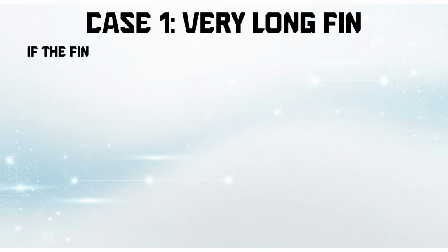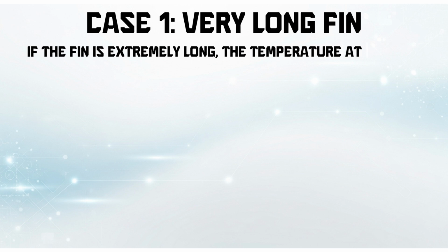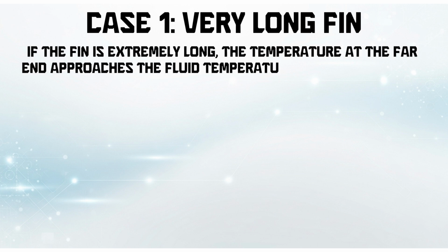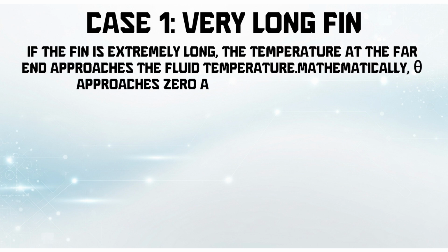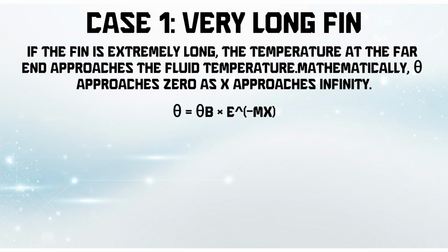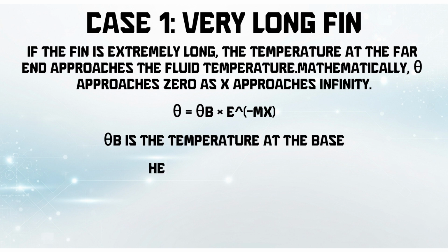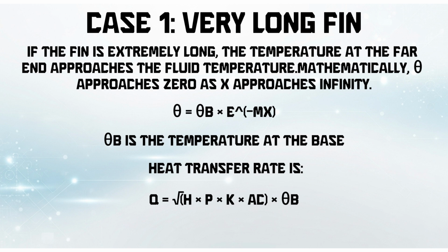Case 1, very long fin. If the fin is extremely long, the temperature at the far end approaches the fluid temperature. Mathematically, theta approaches 0 as x approaches infinity. Theta equals theta b times e to the minus mx, where theta b is the temperature at the base. The heat transfer rate is Q equals root h times p times k times Ac times theta b.